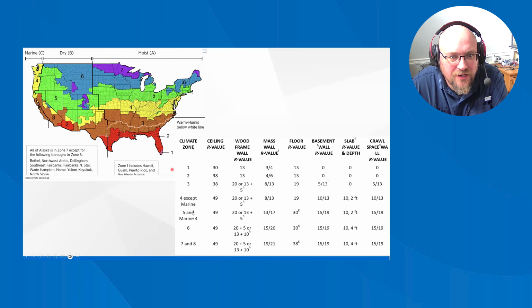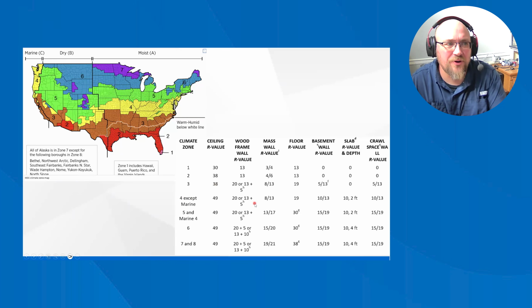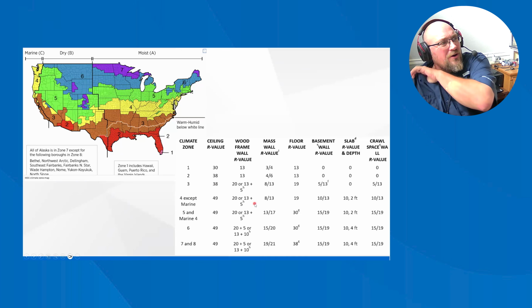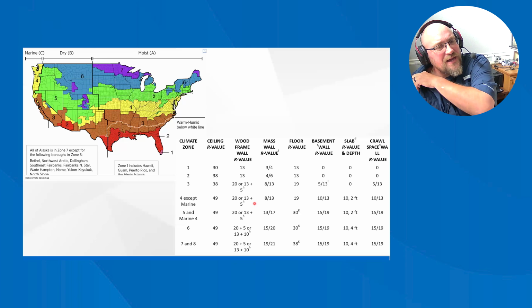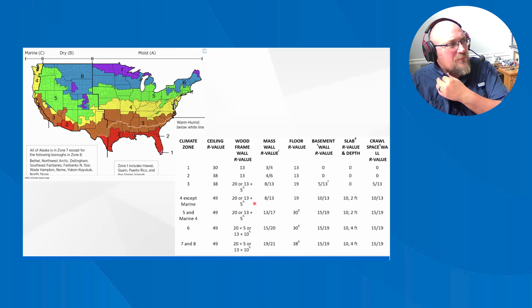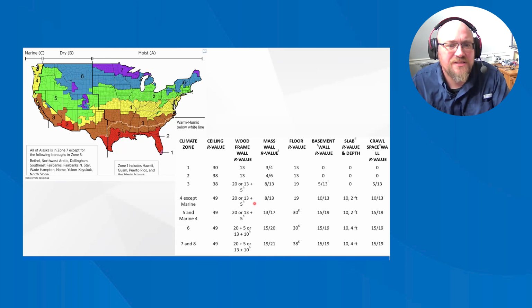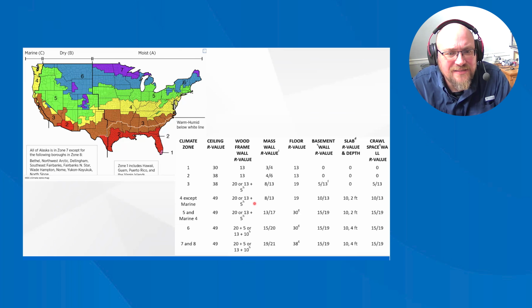We are in climate zone 4, and you can see our R value for the Department of Energy is 49, when in fact our minimum R value is R30 in our ceilings. So again, that just shows you the difference. I have heard that our energy efficiency code is about to be updated. I think they've approved it, but they have not implemented it, where it's going to raise it to R38 in the ceiling as a standard instead of R30.